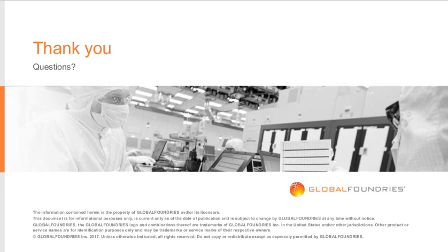The via-tie means it will go through the silicon dioxide isolation layer, so it can conduct the heat to the backside silicon handle wafer. That has better thermal conductivity than the silicon dioxide. There is also a publication by UCSB in the JSSC about the evaluation of this via-tie solution.